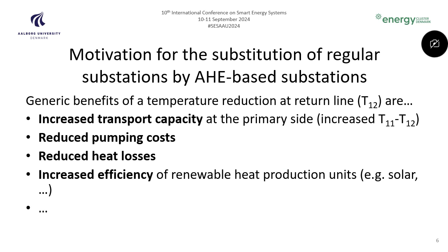Well, why are we doing that? Lowering the temperature on the primary side leads to several benefits. One of them is the increased transport capacity. We have a higher temperature spread on the primary side, the temperature difference between supply and return. It leads to a